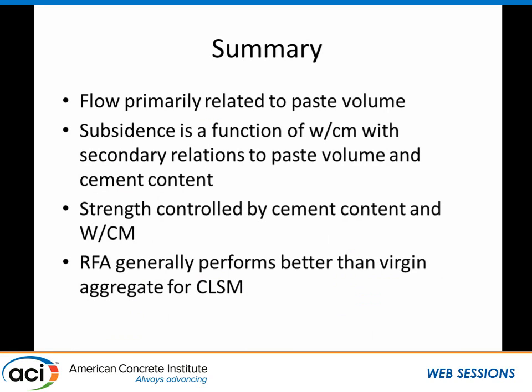So for the summary of this part, the flow was found to be primarily related to paste volume. Subsidence is a function of water cement ratio primarily. Strength was strongly controlled by cement content and water cementitious ratio. And overall, the recycled fine aggregate worked very well and perhaps favorably compared to virgin aggregate for CLSM.